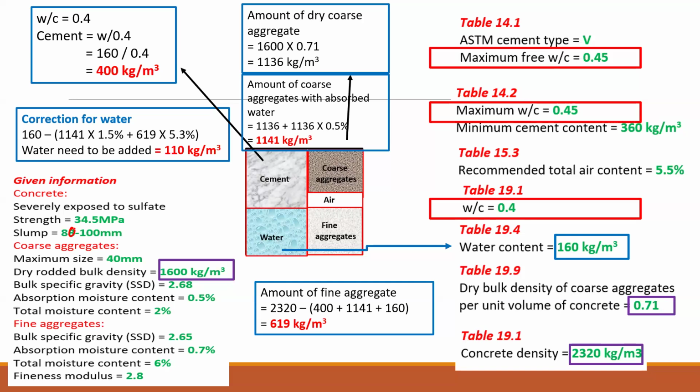Yeah, you mean check that as in the lab before everything, or you could check it on the table? No, you do it in the lab. Yeah, you do it in the lab. Slump test. You have to always write down check. Yes, you need to write down, do a trial mix and check the slump and the strength. Oh, good. Any questions?